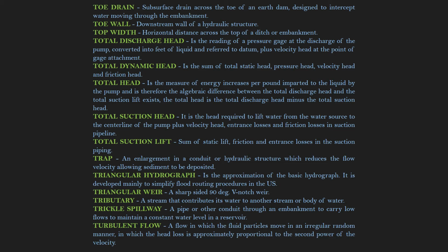Total head is the measure of energy increase per pound imparted to the liquid by the pump and is therefore the algebraic difference between the total discharge head and the total suction lift. The total head is the total discharge head minus the total suction head.